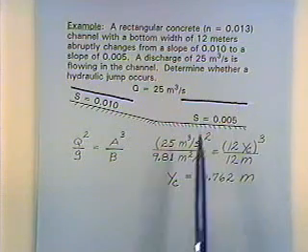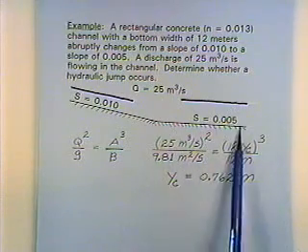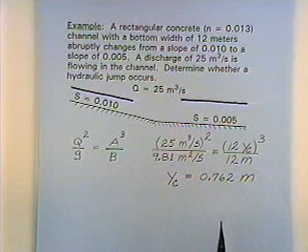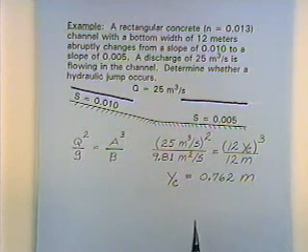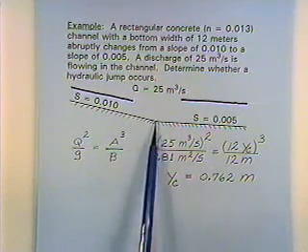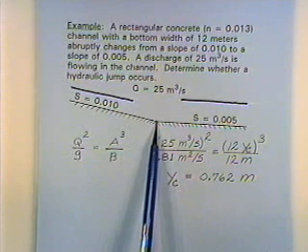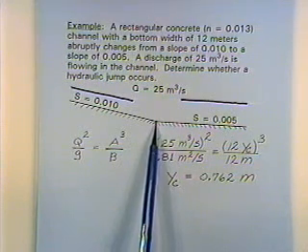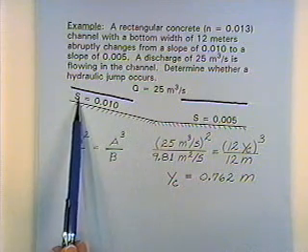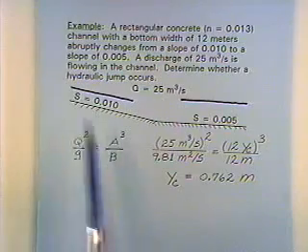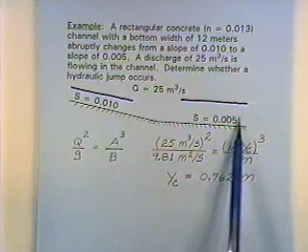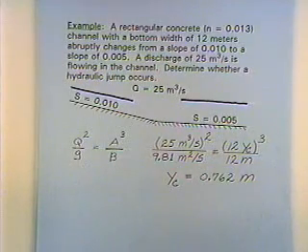And we're assuming uniform flow. We're assuming that there are no other irregularities or non-uniformities to cause any type of non-uniform flow other than this break in channel slope right here. And so if you get some distance away from here where this isn't impacting the flow depth anymore, Manning's equation would describe the flow here some distance upstream and would describe the flow here some distance upstream.